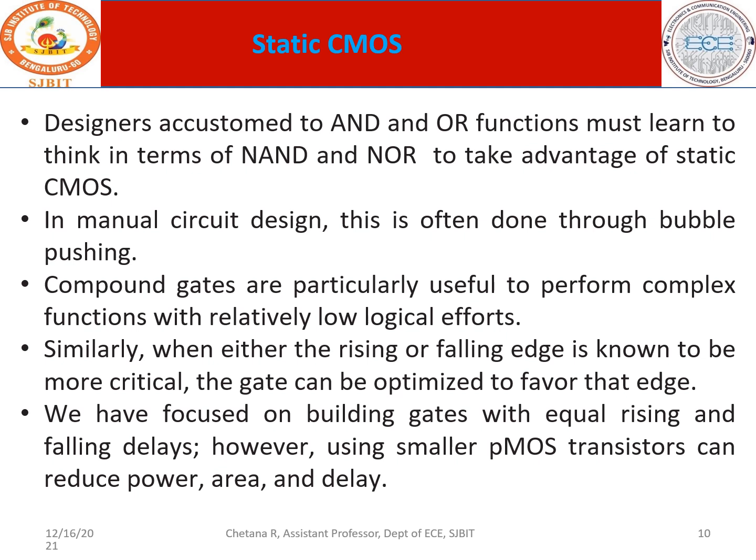Similarly, when it is a rising or falling edge, the gate can be optimized to favor that edge. So what exactly we do is we focus on building gates with equal rising and falling delays, and however use smaller PMOS transistors which can reduce power, area and delay.